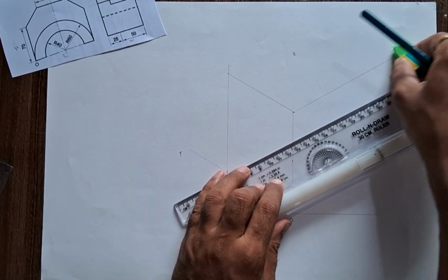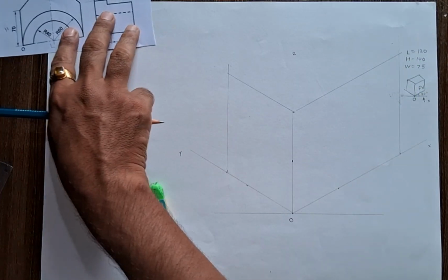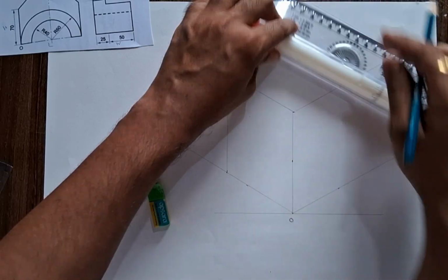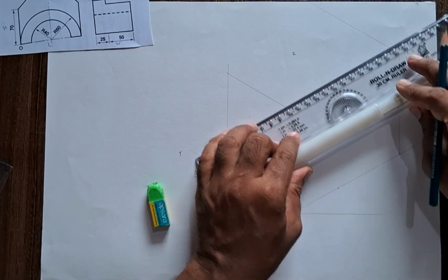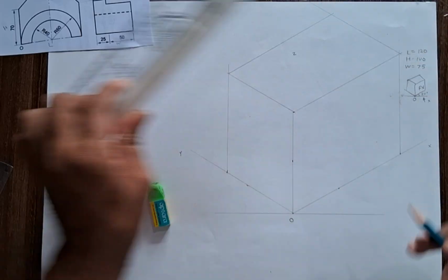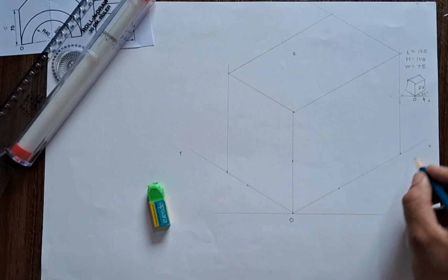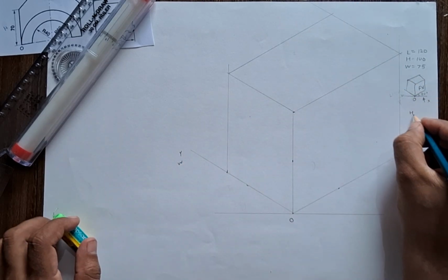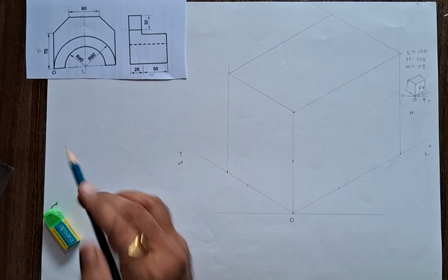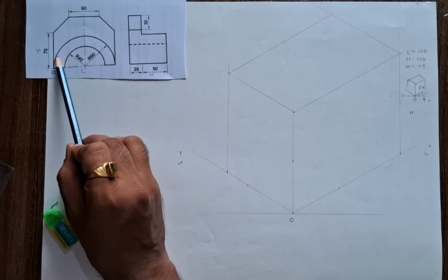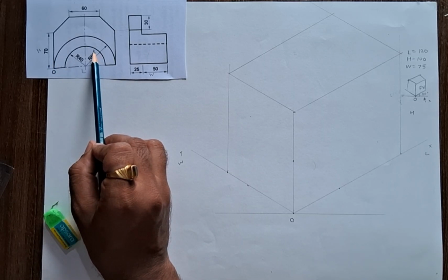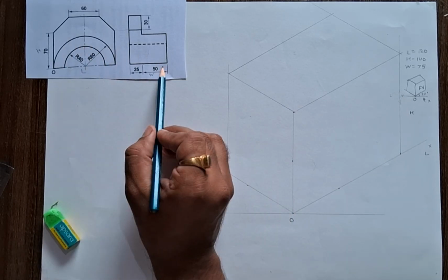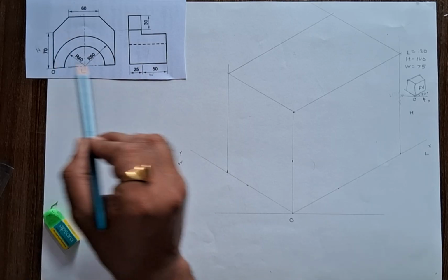These are the two planes. This is a front view plane and this is a left hand side view plane. Now at this roller along width direction, complete a third plane. This is the isometric box for this problem. This is length, width and height. Now you can see here we can draw an outer half circle and inner half circle, and the position of this inner and outer half circle is in this plane only, and the width of this half section is 50 mm and the vertical wall thickness is 25 mm.